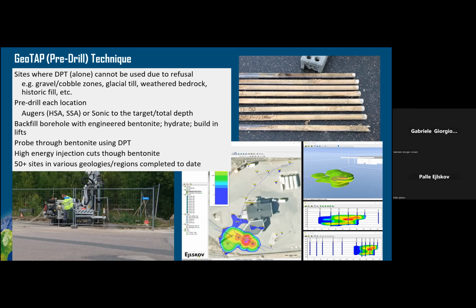So at this site, we applied a sort of horizontal barrier. We performed about 150 drill points to depths between 16 and 18 meters by rotary percussion. We reintroduced bentonite in the borehole and then went down again with direct push. This site was completed in about a month. We achieved no further action a few months ago after proper monitoring was done.